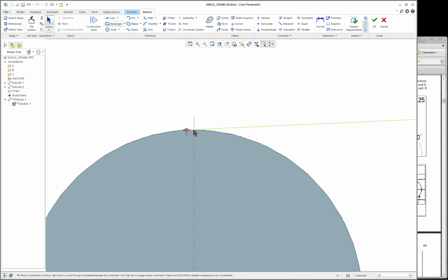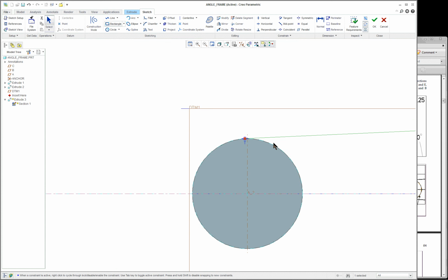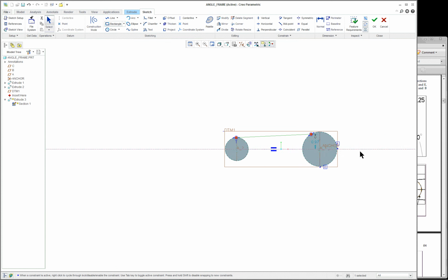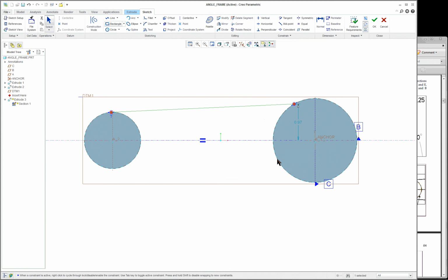Now what I did was I paid attention to staying on the other side of this position right here. This 90-degree position is going to automatically want to lock in. Go a little bit behind this, the tangency T. Now you can always change that, but you can put a constraint on it. Now we're going to put one on the very bottom, same thing. And we could also just do half of it and mirror it.